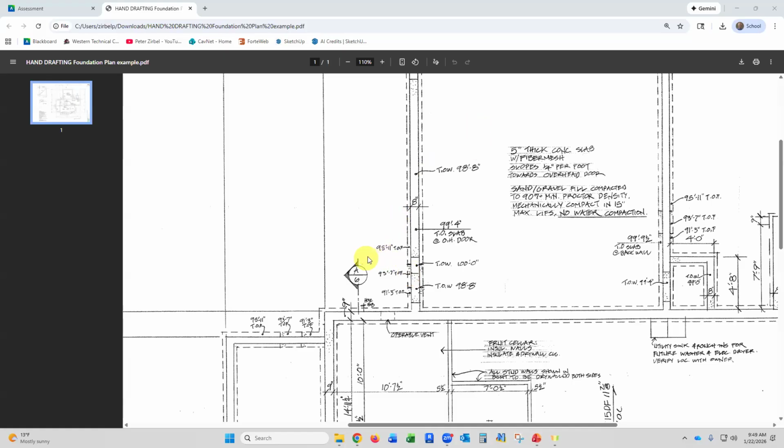Now I've got another step that's 95.11, which is the higher elevation as I'm going around the garage. If I subtract 93 feet 7 inches from 95.11, how much is that step? 2 foot 4 again, right? Because 11 minus 7 is 4, and 95 minus 93 is 4.